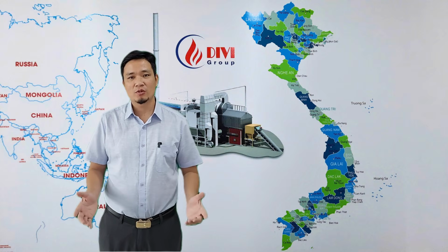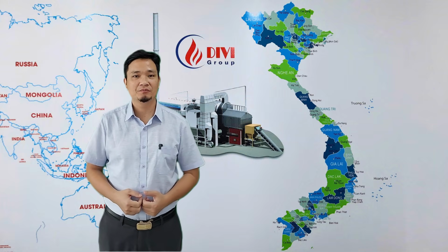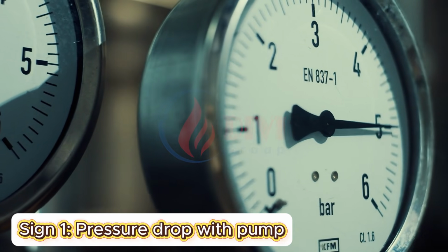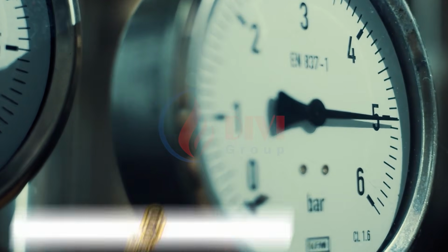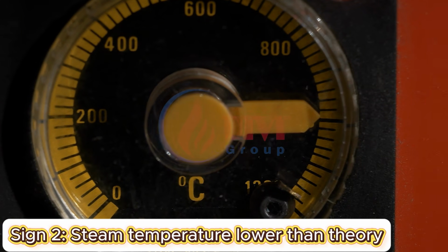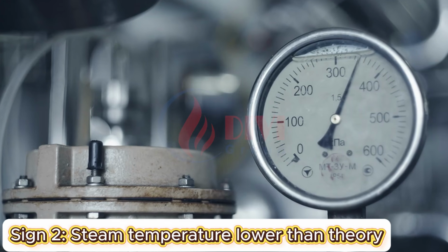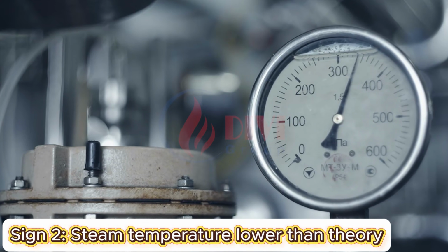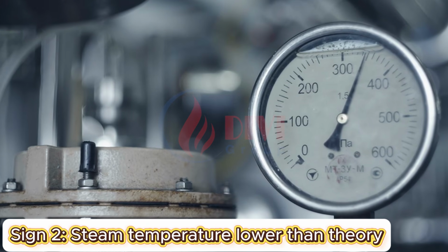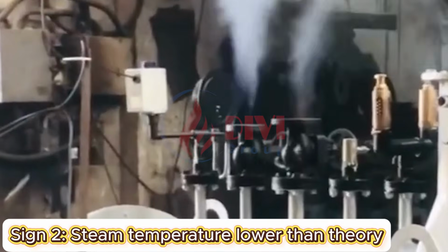So how can you know if your boiler is producing wet steam? There are 2 signs and 1 direct inspection. First sign, whenever the feedwater pump runs, steam pressure drops. Second sign, measured steam temperature is lower than the theoretical saturation table. For example, at an absolute pressure of 9 bar, the standard saturation temperature is 175.4 degrees Celsius. But if your actual reading is only around 172 degrees Celsius, the steam is definitely wet.